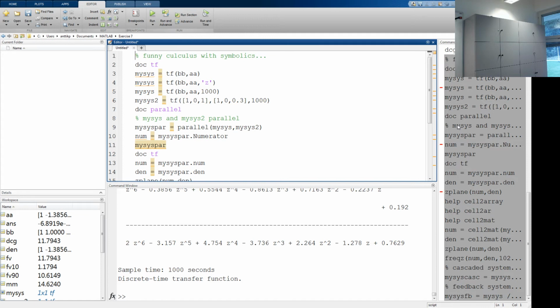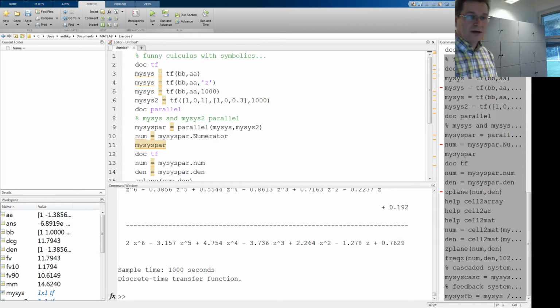Maybe. But fiddle with the P, I, and D values one by one, so that you get, as I asked there, better rise time, better settling time, and smaller overshoot. I'm not telling how much better. You can define it yourself.